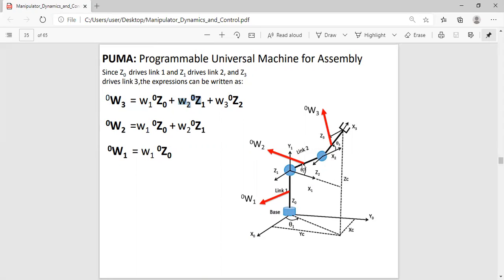If a joint is a translational joint, it doesn't result in an angular velocity. So let's say joint 2 is translational. In that case, you don't have rotational components, so you don't have an angular velocity component as a result of that, but you do have it as a result of some other joints which are rotating it. So you get the point, you don't add that contribution. Okay, so we're good here.